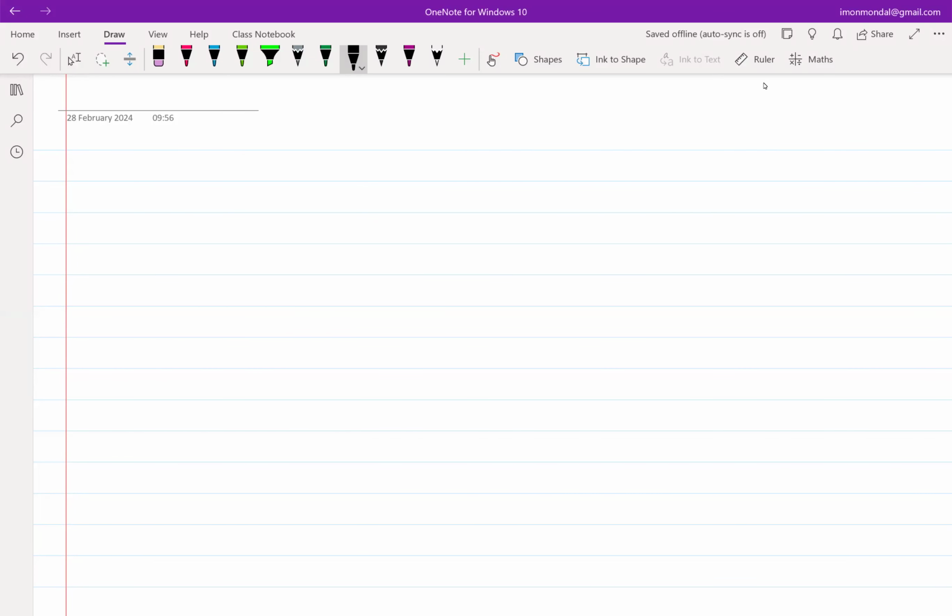In the last class, we started looking into another complementary device. The first part of the course was concentrating on mostly PMOSFETs, right? And then in the last class, we said that if we invert all the dopings that constitute a PMOSFET device, we'll get another device which is a complementary device. But in that case, the carriers of transport will be electrons instead of holes, right? So that's essentially the fundamental difference between an NMOSFET and a PMOSFET.